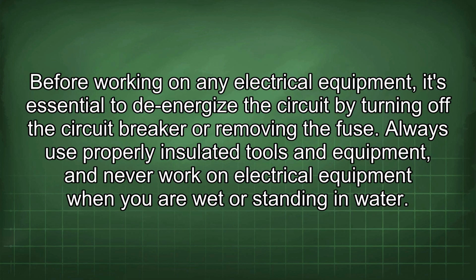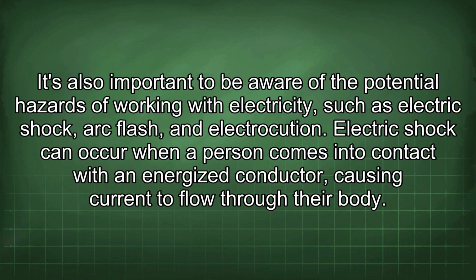Before working on any electrical equipment, it's essential to de-energize the circuit by turning off the circuit breaker or removing the fuse. Always use properly insulated tools and equipment, and never work on electrical equipment when you are wet or standing in water. It's also important to be aware of the potential hazards of working with electricity, such as electric shock, arc flash, and electrocution.